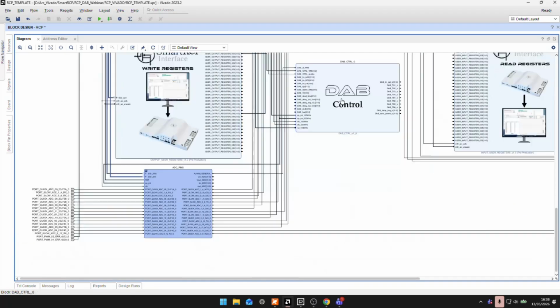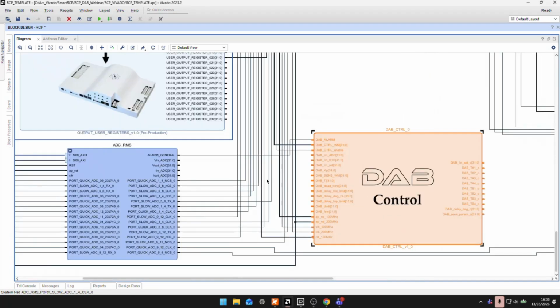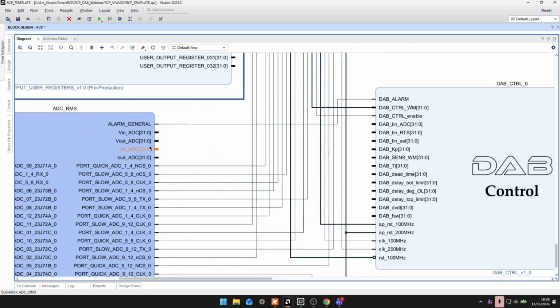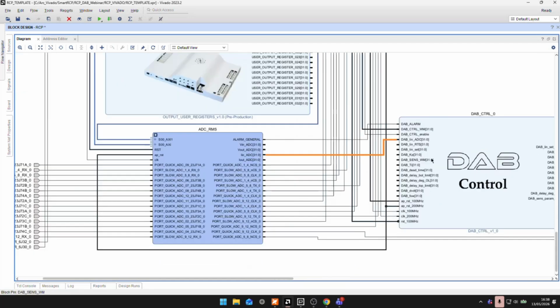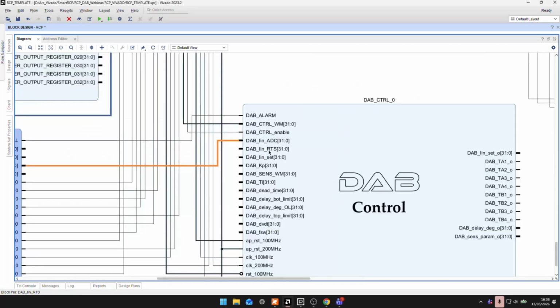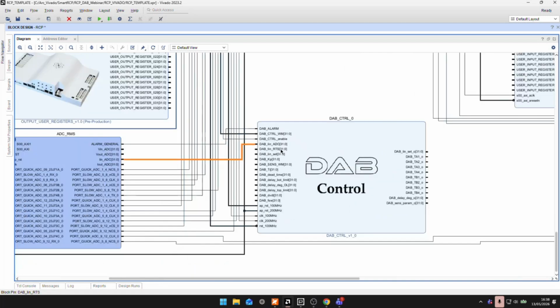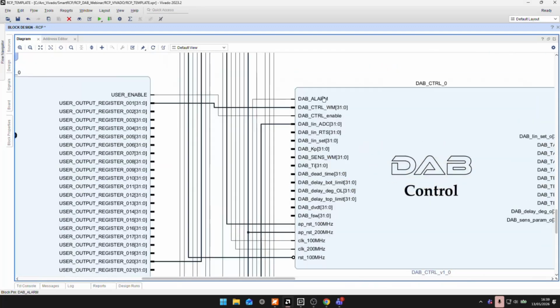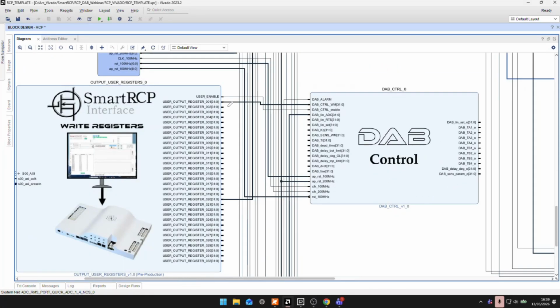So we have to move over here and connect the input current that we are measuring here in the ADC block to our IP. As we can see here, the next signal is the input current, but the one obtained with the RTS model. So we are going to connect this signal later, and I'm going to move on to the rest of the signals that we have here.